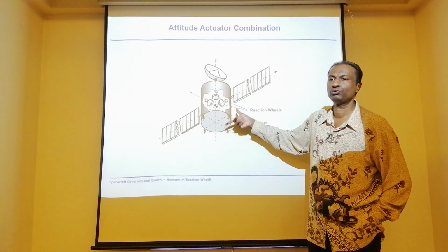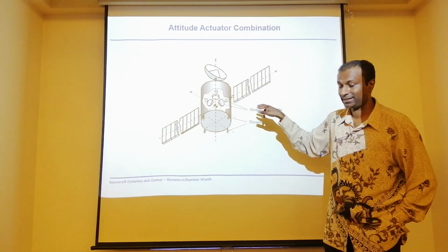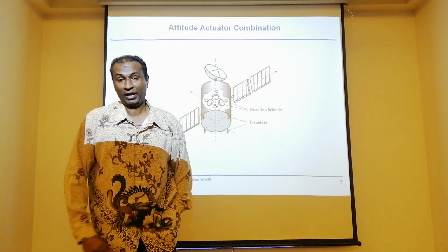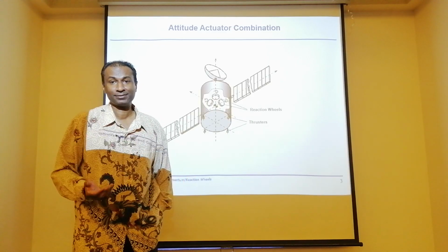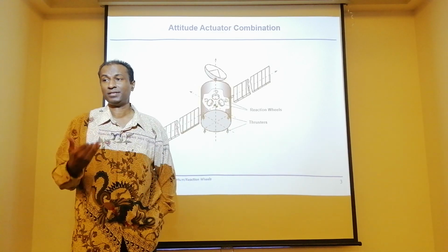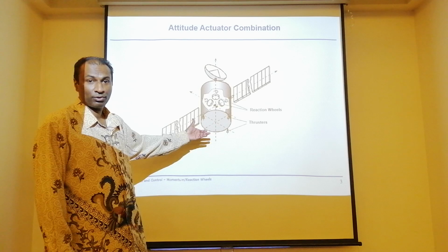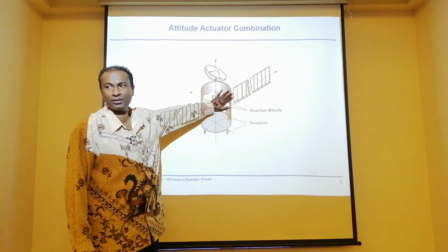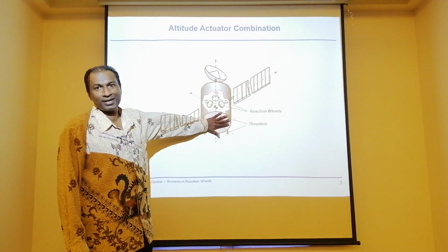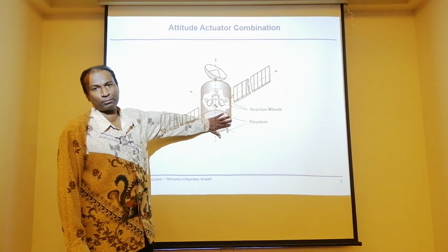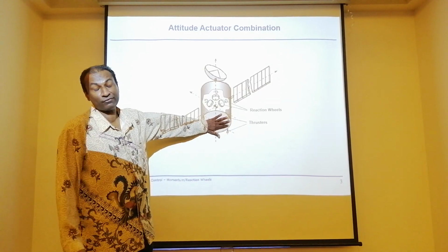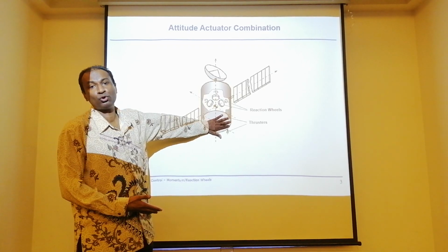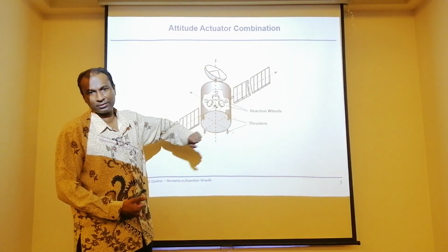It should be doing both, which means the life of the satellite can be long, can be 5 years, can be 10 years, can be even 20 years when you have this system. But assume you don't have thrusters, you only have reaction wheels, you'll be lucky if the satellite lasts for about 3 years or even 4 years if it is a low Earth orbit satellite. Okay?